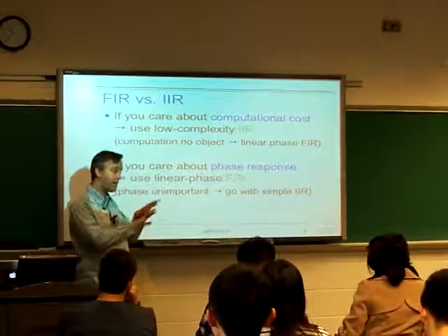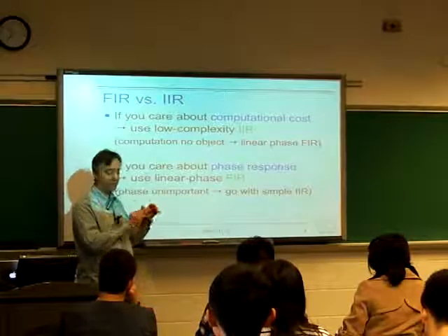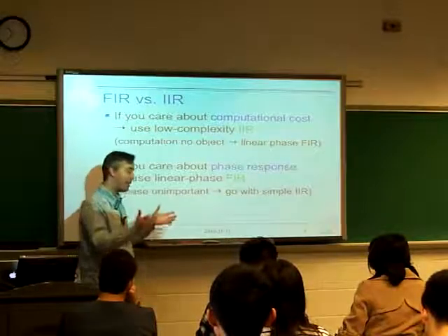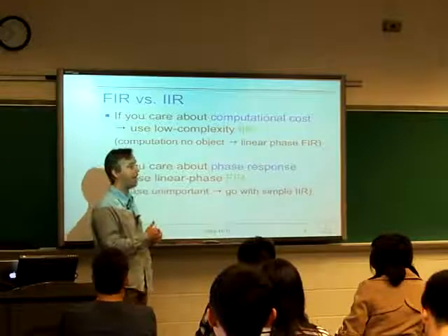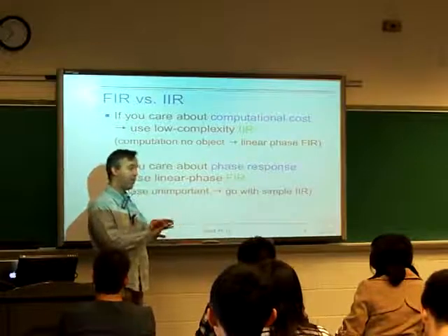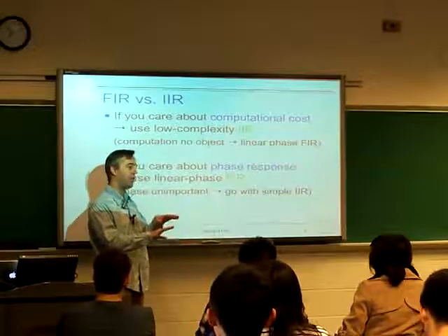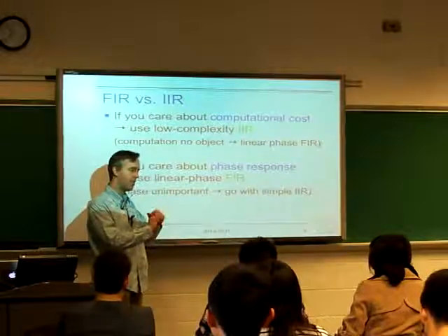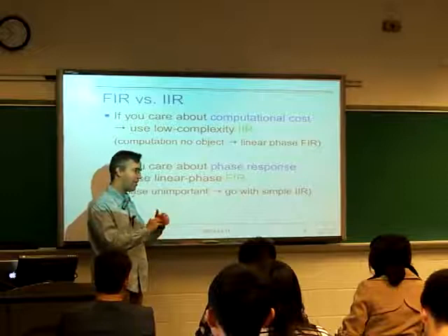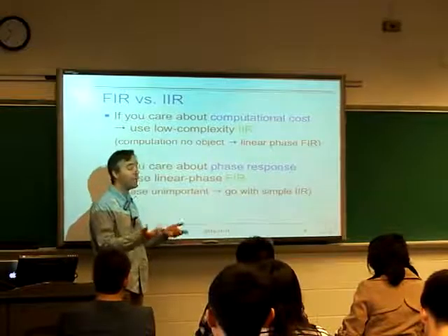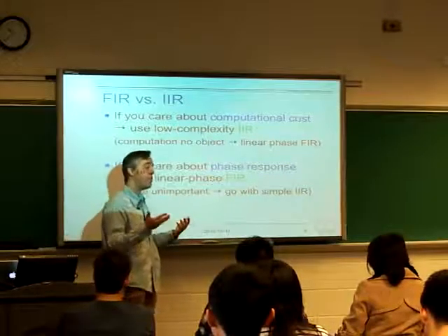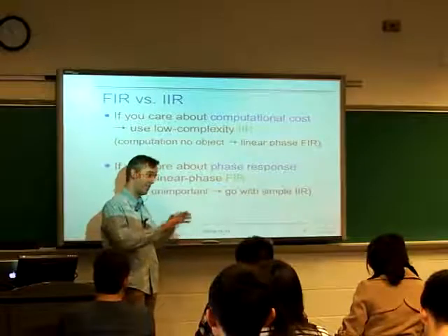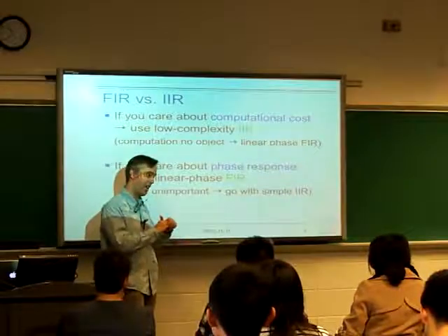So if we think about it in terms of relative delay, you're building maybe an analog low-pass filter, and there's a little bit of phase distortion. But the phase distortion may be on the order of milliseconds. So maybe some frequency components will be skewed relative to others by a thousandth of a second. If you're dealing with audio, that's not important to your listener. They're not going to notice a millisecond change, right?